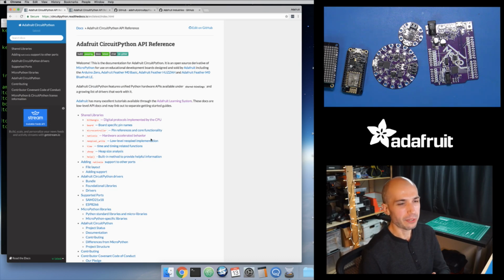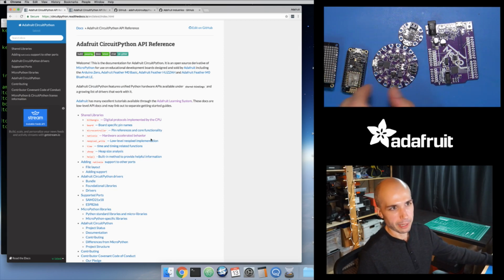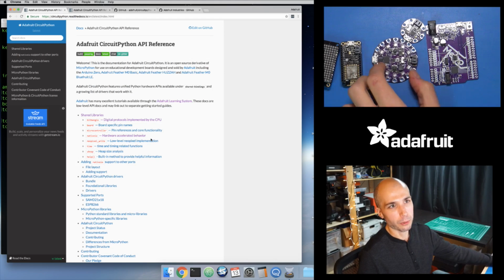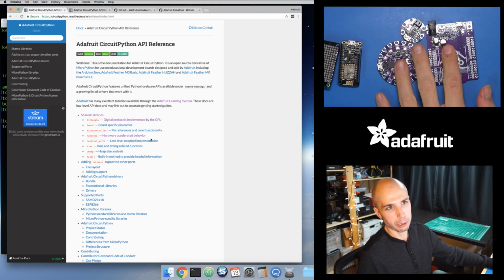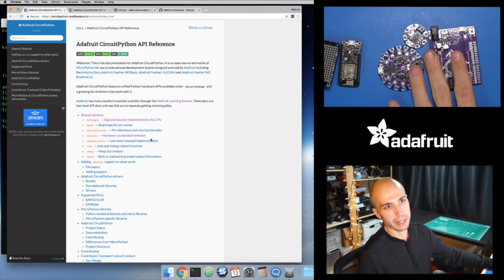But it would be really confusing if you saw this as Adafruit MicroPython and thought, isn't it the same? No, it's different. So that's why the naming is different, and also why some of these modules have a different name. So, for example, if you take code that's written for a MicroPython board that uses the machine API and you try to use it on a CircuitPython board that doesn't have the machine API support, so the ESP8266 would have the machine API and potentially work, but for some of these boards with the smaller processors like the SAMD, you try to run that code, it will fail.